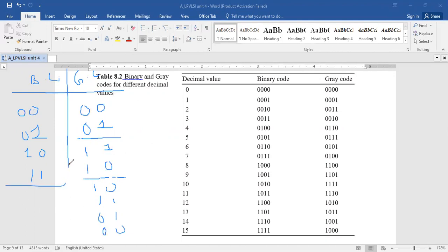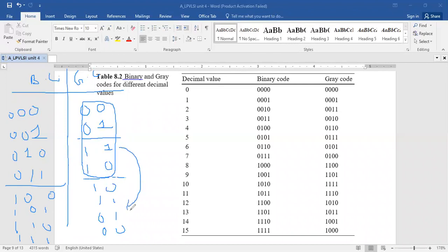And if you're considering a 3-bit combination, 2 bits are given by a mirror image. This is a 2-bit combination. This is mirror imaged here. Now, for the third bit, you just transfer the bit combination as it is here: 00, 00, 00, 00, and 1, 1, 1, 1. Right? In this way, you'll be forming 1-bit, 2-bit, 3-bit gray code.